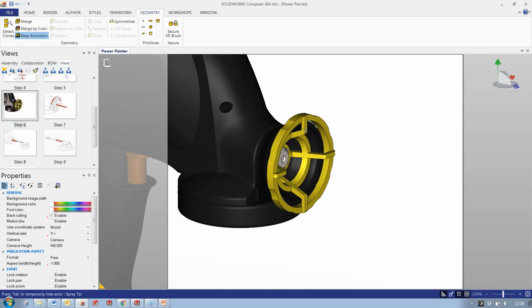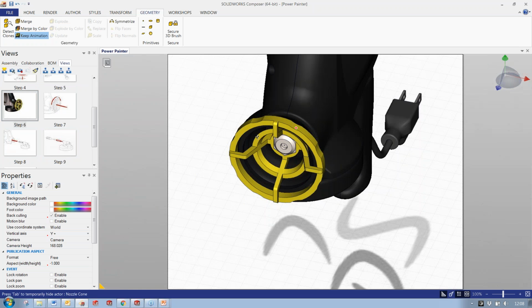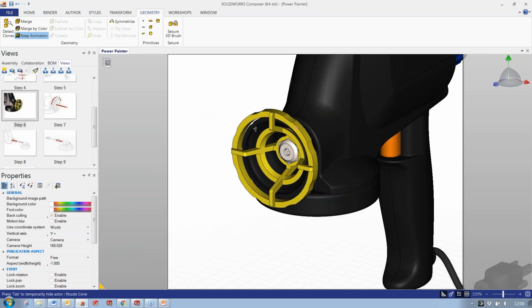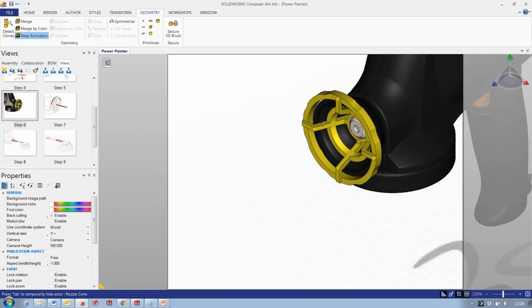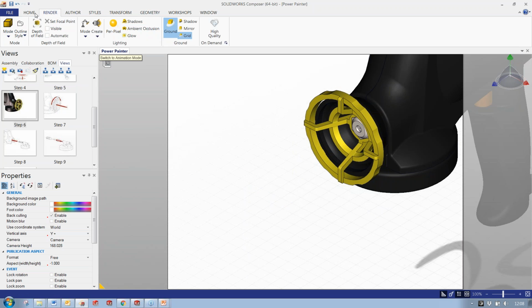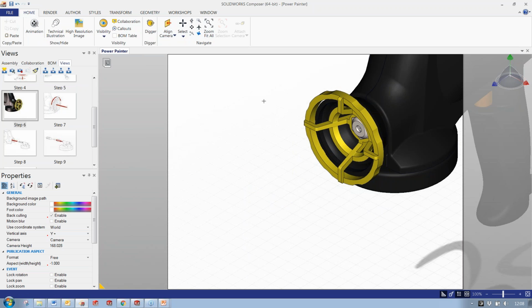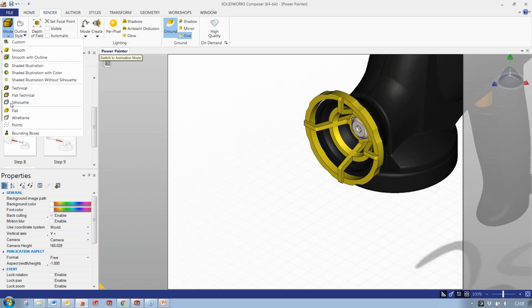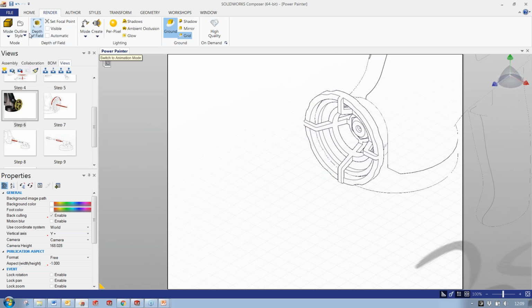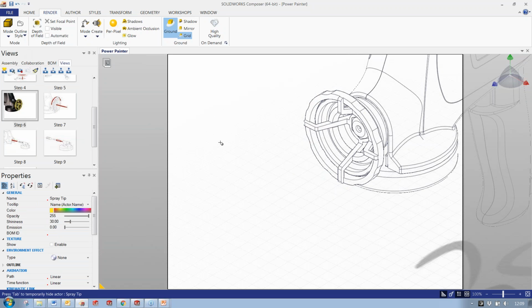and we're just going to quickly go through the process of being able to manipulate our model. So just basically rotating it around, and this is done in much the same way as SolidWorks. Just turning off one of these features here. Basically, the first thing I need to do is change the render type. I want it to be a silhouette render. You can see some of the tangent edges are missing there. We can show those by going to construction edges there.